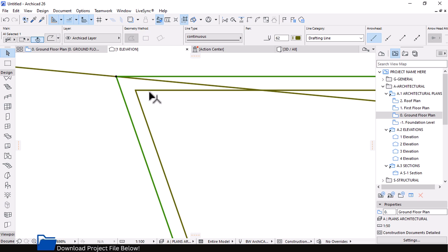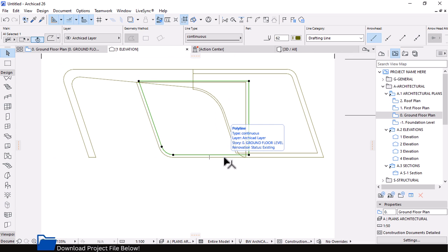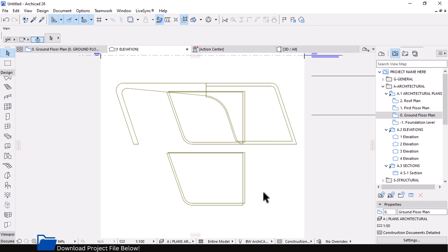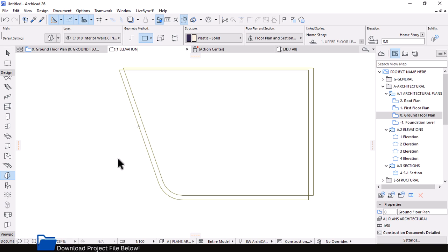Let's say 180. And then we're going to close it off by selecting this line or this edge and offset it to the top like that. We do the same to the side just to close it off. And then let's select these 2 lines, drag a copy to the bottom, and we're going to pick a morph. Within this morph, we're going to activate the magic wand by hitting the space bar and holding. You see, I'm picking only the region, unlike before. I'm not picking the edge, I'm just picking this region that is defined by these 2 polylines. And then click on it.